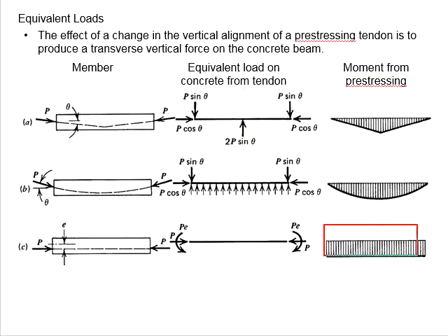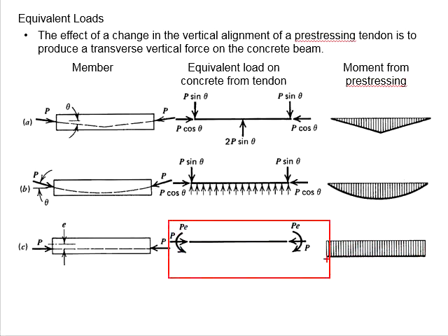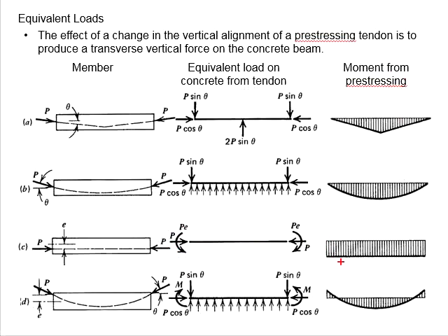Or you can look at this example. If the beam member is subjected to only bending moment, which gives a constant bending moment diagram, this setup may be applicable. Similarly, for a continuous member, where there are fixed end moments generated as a result of the stress transfer, the effects of the UDL load can be best counteracted with this setup of the tendon.